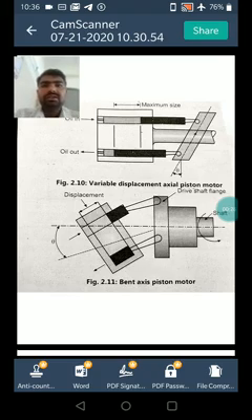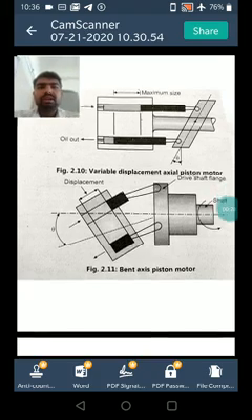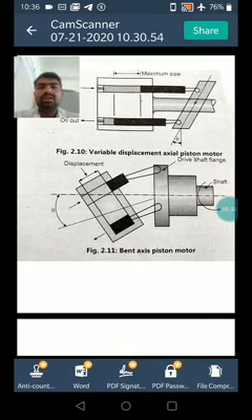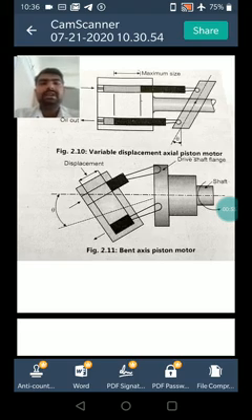These are similar to the axial piston pump shown in the first unit. The units which work like pumps or motors are available. However, units with a seat valve cannot have reversibility of their function. The fluid pressure forces the piston outwards, and the reaction force slides it up against the fixed swash plate, which produces a tangential force causing the piston block and output shaft to rotate.